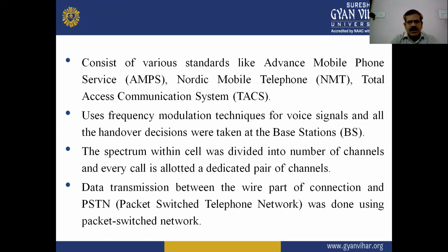It used a frequency modulation technique for the voice signal, and all handover decisions were taken at the base stations. The spectrum within a cell was divided into a number of channels, and every call is allotted a dedicated pair of channels. Data transmission between the wired part of the connection and the PSTN was done using a packet switch network.